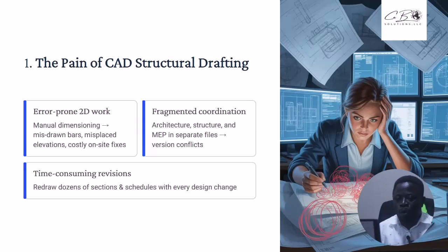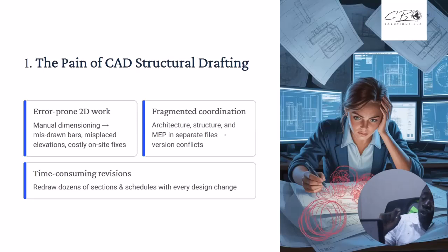Look, when you are detailing a slab, and you start counting, sometimes when you are labeling R12 01 at 150 centers, and you come to the next one, you have to be observing and renaming as a bar of the same length, the same shape, the same thickness, by the same name. By the time you finish calculating, punching your calculator, look, you'll be confused. Then you say, but my last count was 100. Charlie, I think I have skipped some. So let me add 20 rods in there. If what you missed were 5 and you've added 20, that extra 15, who does it go against?